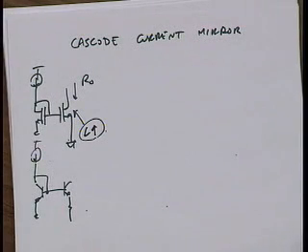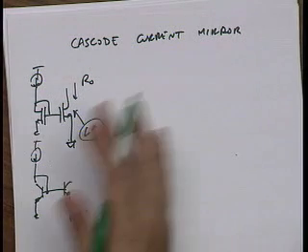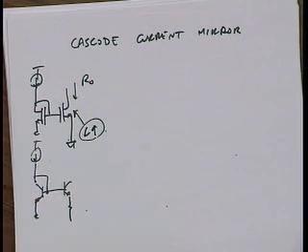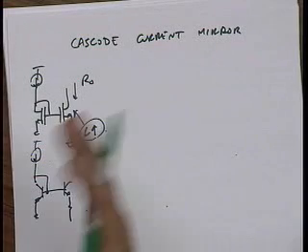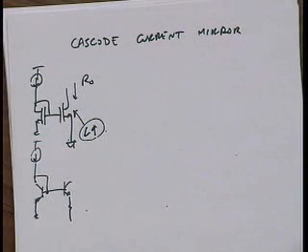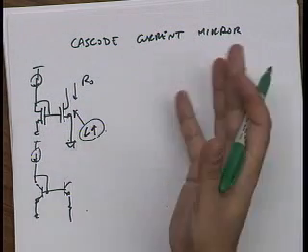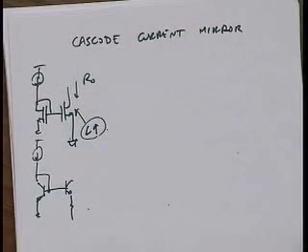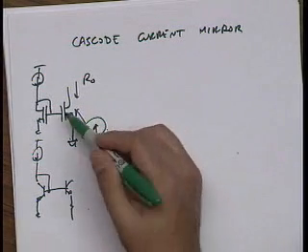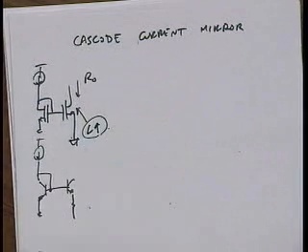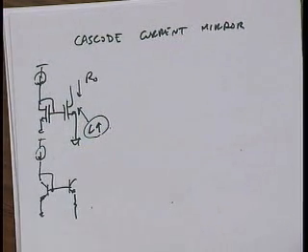So for instance, if you're in a 90 nanometer technology node, don't design your current sources with 90 nanometer. Design them with 1 micron or half a micron. The way you know what to use is you'd generate some plots, and you'd find out that, say, beyond half a micron, the benefit you get in RO with channel length scaling saturates. So half a micron may be the optimal point. In 0.18, you can run some simulations and find out what's probably the best point to use. Otherwise, if I use the longest channel length, I can always adjust the output impedance by playing around with the W of this device. Okay?